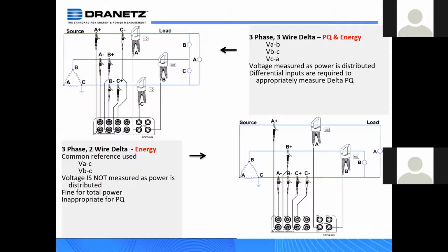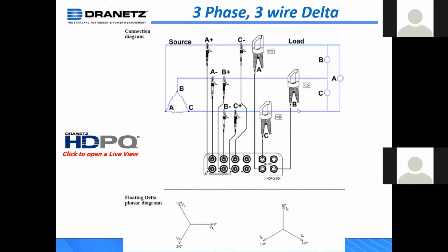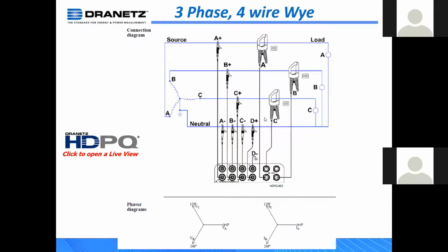Okay, so we have a question from Patrick: when measuring on a Delta 480 system, is there any benefit to connecting the D voltage channel to ground? Well, there's no benefit in your primary phases, Patrick. However, the one thing you need to be aware of, if I go back two slides, is this 3-phase Y situation. I have 2 choices when I'm connecting my instrument to this. I can connect it phase to neutral, or I can connect it phase to phase.